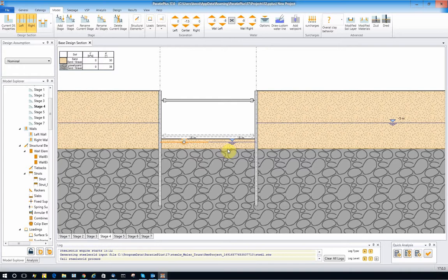I want to stress that this is not a true seepage analysis, but is simply a method to calculate the pore pressure according to a simplified scheme of seepage that depends just on the path of the flow very near to the wall. This is normally a typical assumption that is also considered to be quite conservative. In another video we have seen that there are also other possibilities.